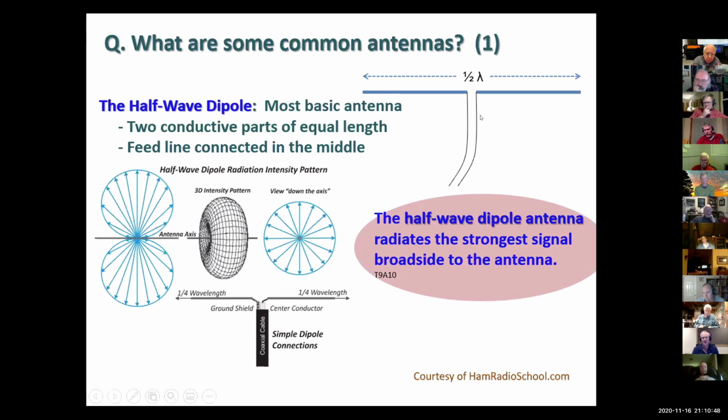But you would tend to see a balun where you go from coax to the twin lead. Ladder line, yeah. A lot of times you'll have an antenna tuner that can actually handle the ladder line directly. It's got two banana posts. That's another configuration, and then it'll match to the coax connected on the other end. Yeah.